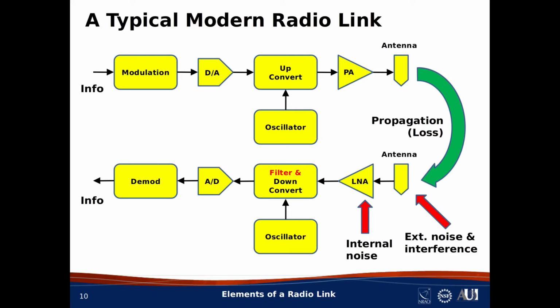Now, once again, I want to emphasize that what I'm showing here is only one of many possible architectures. Single conversion superheterodyne architecture means that the modulation processing and the RF processing happen at different frequencies, and the conversion between frequencies is accomplished by mixing the associated signal with the signal from an oscillator.